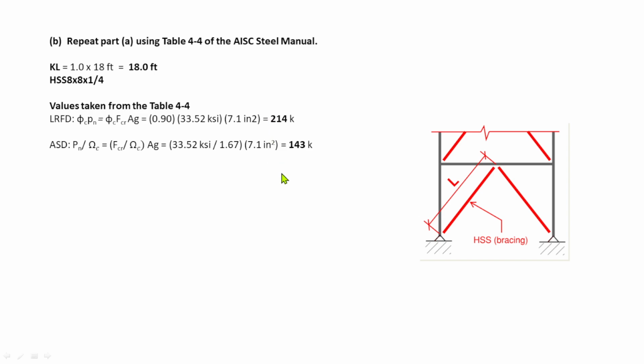So guys, if you find these values from the equations of the AISC manual, you can compare them with the forces, if you are modeling the structure in whatever program you are using. Then you can determine whether the member is passing or not. If it is failing, maybe you can increase the thickness. It depends on your judgment.